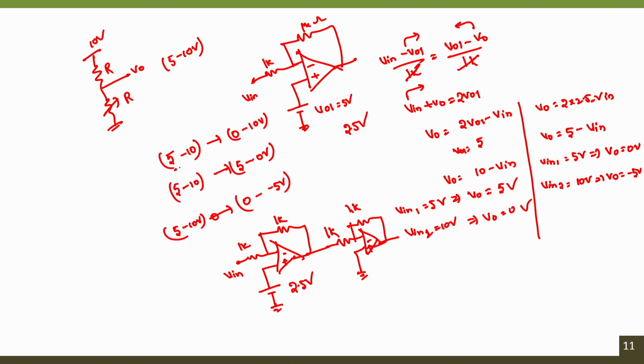So, for an input voltage of 5 to 10 volts, we will get an output of 0 to 5 volts within the same phase. Because of the offset and the inverting amplifier configuration, the single operational amplifier, though it is providing the required voltage, with the offset of 5 volts completely eliminated, is creating a shift in the signal. So, to avoid the phase shift, again if you use an inverting amplifier configuration, which has a phase shift of 180 degrees, because of that phase shift the minus will convert to a positive.